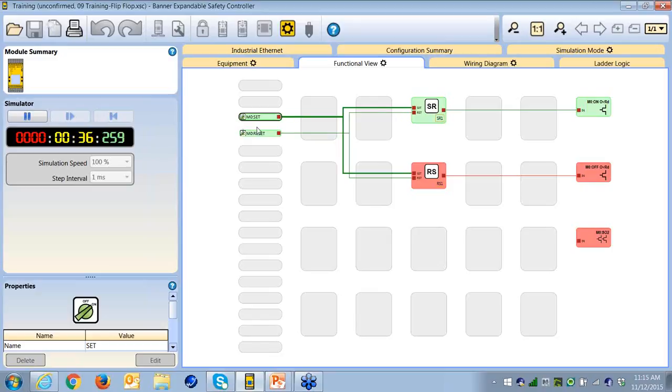You want to decide, should that happen, what do I want my output to be? In most cases, in the safety function, if this leads directly to shutting off a safety function, you do not want to use an SR. You want to have it off override. Unless, of course, you're designing some pumps on submarines, in which case the on may be the safer of the two modes.